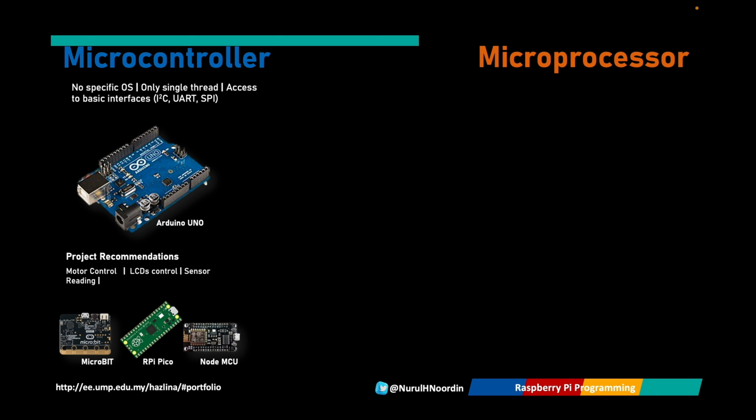A microcontroller, like the Raspberry Pi Pico, is designed to handle specific repetitive tasks with low power consumption. So, it is energy efficient, great for battery-powered applications. It can do real-time processing, whereby it can instantly respond to sensor input. No operating system is required. The firmware runs directly on the chip. However, Raspberry Pi Pico has limited processing power, so it is not suitable for complex computing, the kind that involves a lot of calculations. It has no multitasking capabilities because it is designed for single-purpose applications.